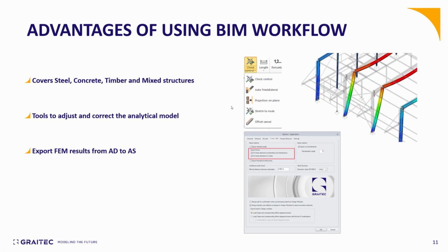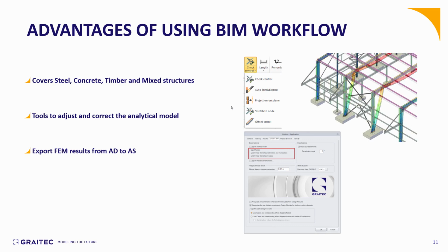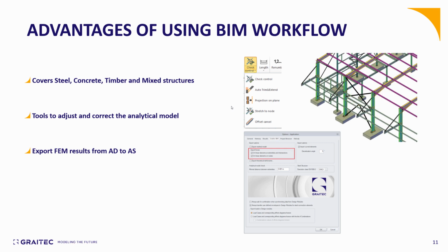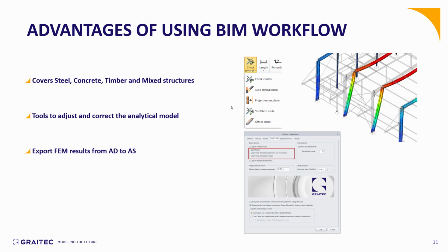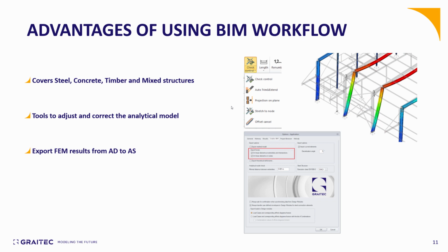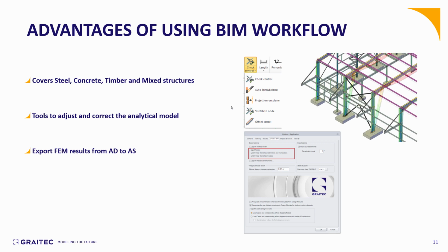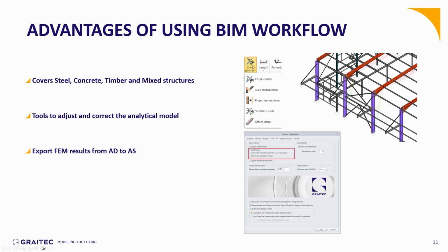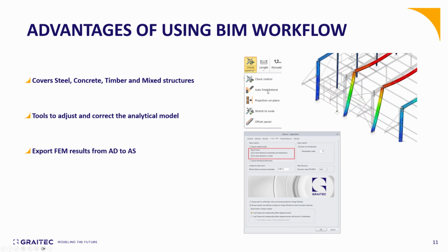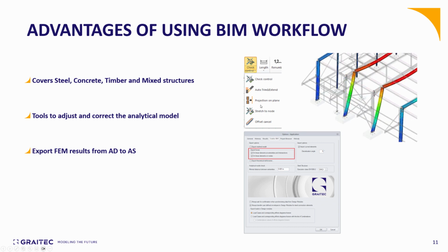So the other benefits of the beam workflow, again, it can also work on mixed structures. That's one thing. The other thing is you should have a proper model when you're sending your geometry inside Advanced Design. And actually, this is correct for any structure software. So you should have your analytical lines correctly connected in nodes, so loads can be transferred. If that's not the case and you have some problems, in Advanced Design we have a check and control tool that you can use to check if there's an instability or a discontinuity in the model. And also we have tools to fix that.